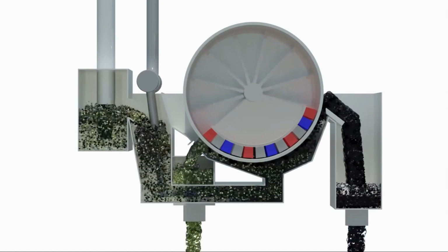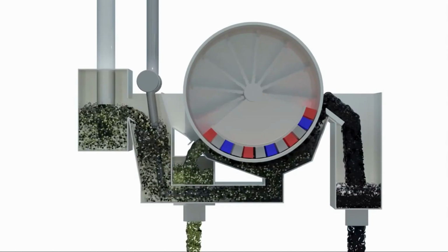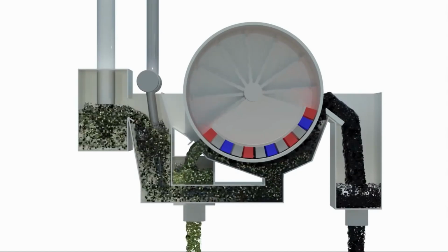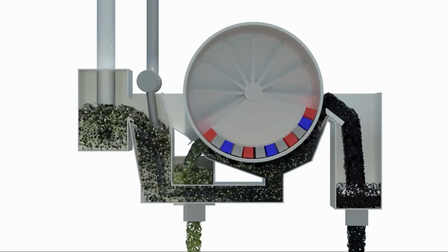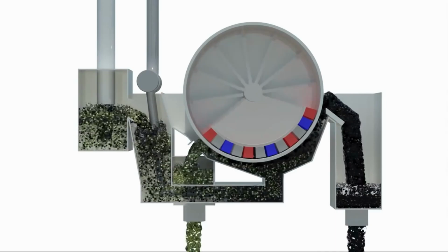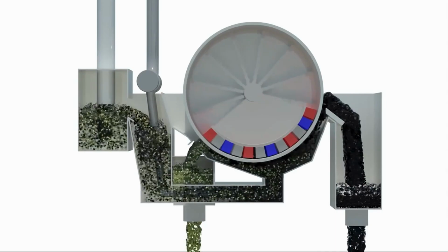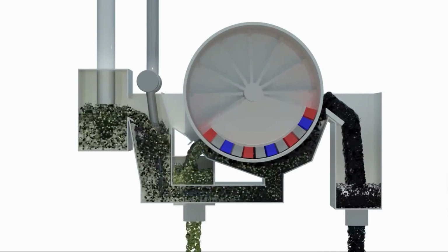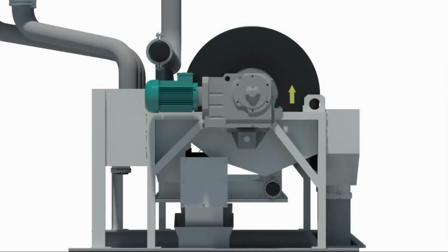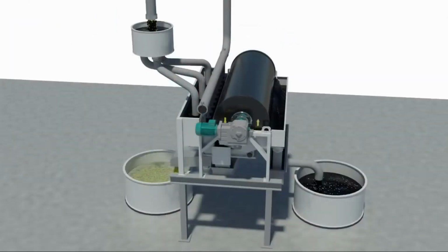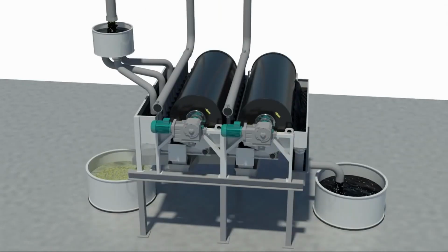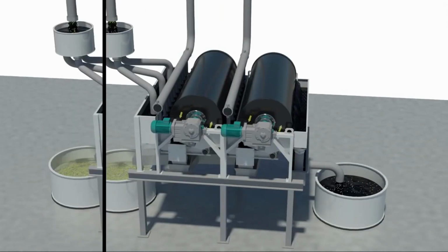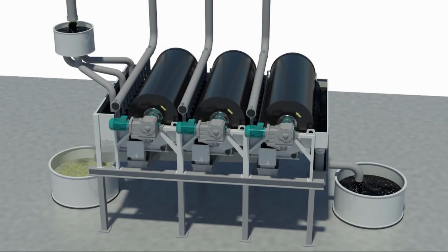It's going to be accessing the equipment from below, and as you can see, we have permanent magnets installed inside of the drum. To the right hand side we're going to have our magnetic concentrate, and on the left hand side we're going to have our non-magnetic material exit the machine, and it works quite well. And we can even assemble more than one. It's quite regular to have an assembly of all of this material.